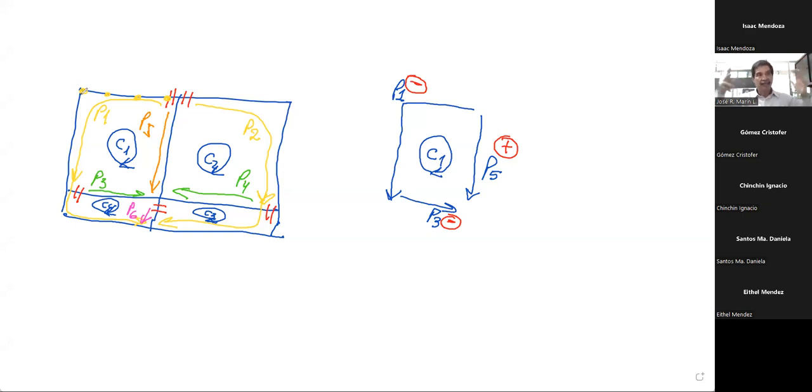And the shear stresses, remember that on the sides, are very important. They decrease a little bit from the neutral axis when you go up, but still, on the side, they are important. So in the connection between the deck and the side, in general both normal and shear are important, and then you have to combine. As a result, in this area, usually you put a little bit more thickness.